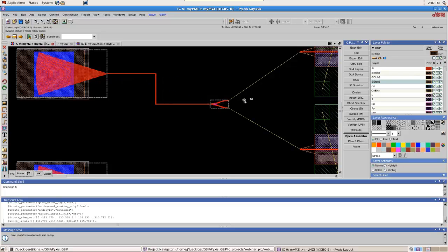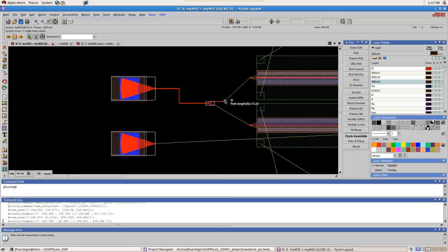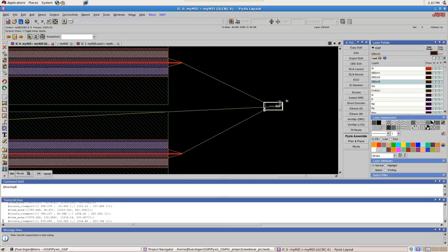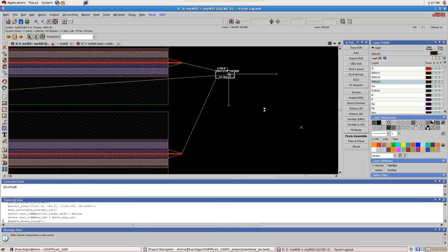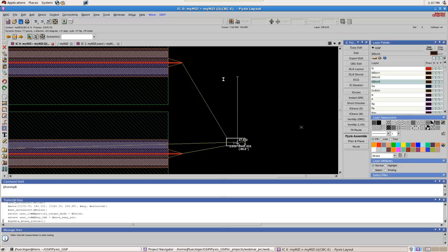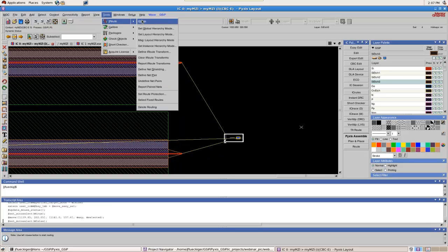And you see that right now by default we're setting all these waveguides with sharp corners. So we don't want to have that when you fabricate, but this is the way you're gonna get started here. So you're gonna set all the waveguides, and this is the optical part first, which for the modeling part will be enough to get started. So this is what I was actually moving around the Y branch, so we get now different distances for the two arms of the modulator, so then we can have an unbalanced modulator.